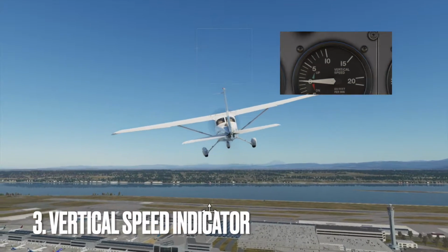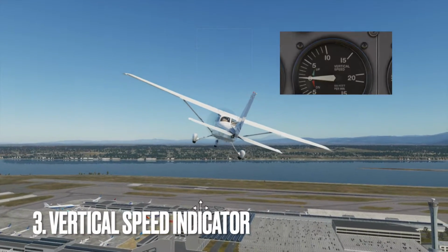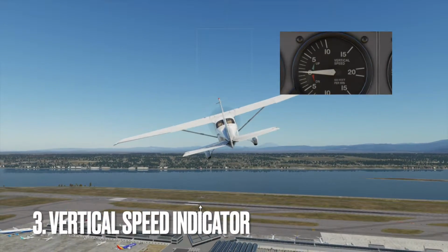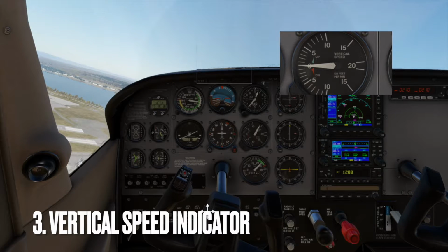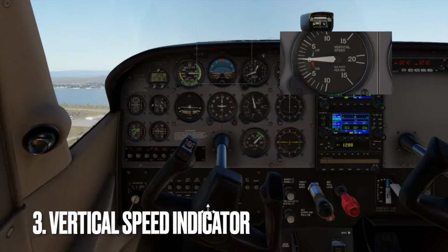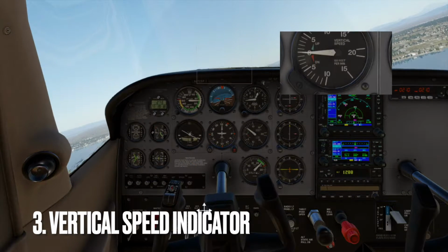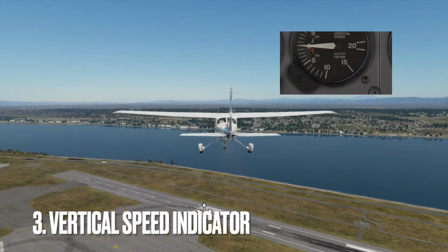The vertical speed indicator shows the rate of climb or descent in feet per minute. Pilots use the VSI to control the aircraft's vertical speed during ascent, descent, and level flight. For example, when leveling off at a cruising altitude, the VSI helps the pilot adjust the aircraft's pitch to maintain a steady altitude. Monitoring vertical speed helps pilots maintain altitude control, especially during instrument flight and in congested airspace.